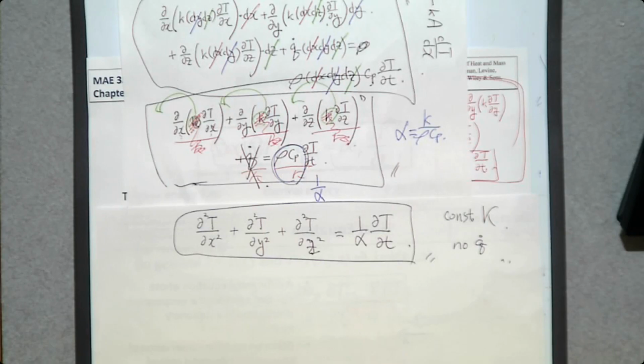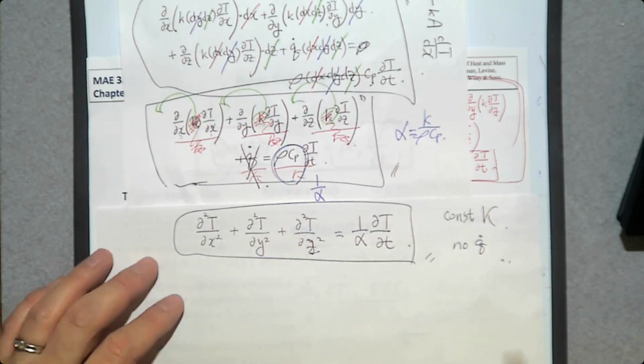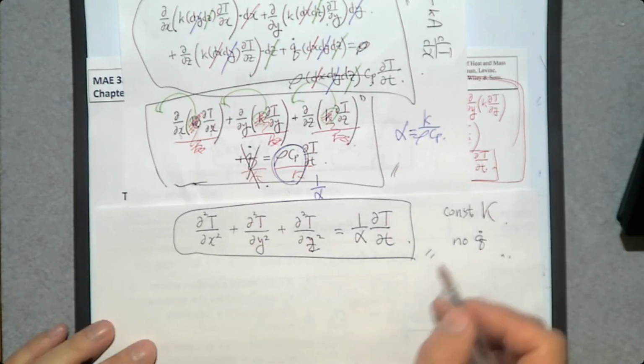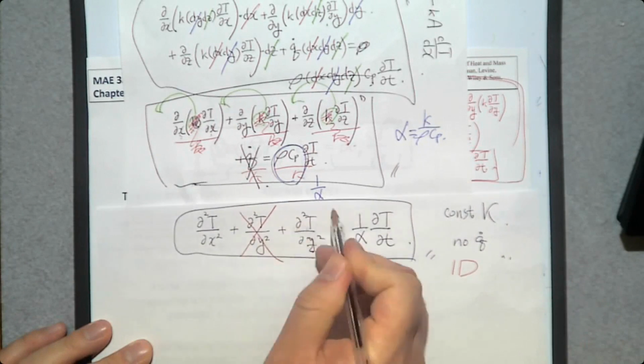What about all the way to the right and then go out, or just come out? If you are heat, you will choose the fastest way, right? So the majority of the heat transfer in the cell phone is going to be this way or this way. Then, do we need to consider X, Y, Z all together when you talk about heat transfer from the cell phone? No, only one direction. Then can we say one-dimensional heat transfer? Yes. In what direction? Are you going to choose Y or Z? You can do so, but most likely it is reasonable to choose X. Then if we say one-dimensional heat transfer, you can neglect these two.